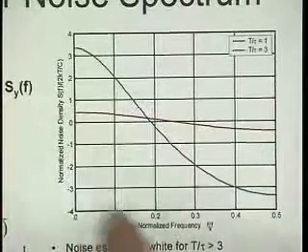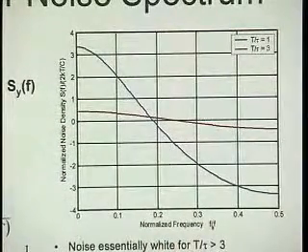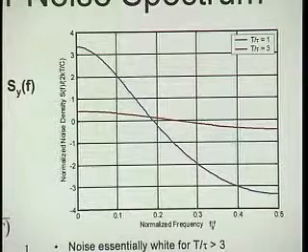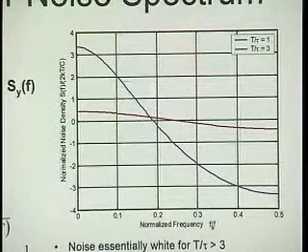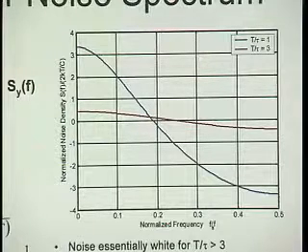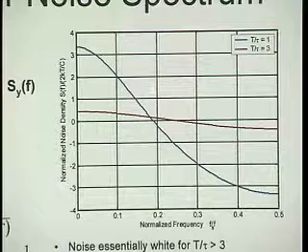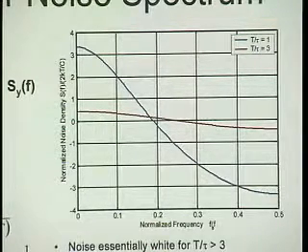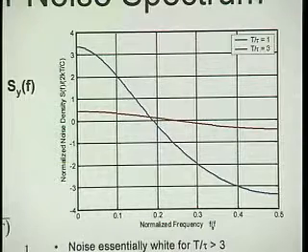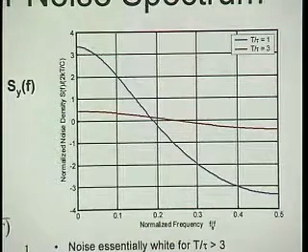I mean, this is within half a dB. That's kind of the question: how much should we bang on SPICE to get a good agreement? If you know the noise of your system to within a couple of percent, you're done. Why? For example, the temperature changes a little bit, and that changes your noise by more than a couple of percent. So we really can't cut it with noise to 3 digits after the comma.